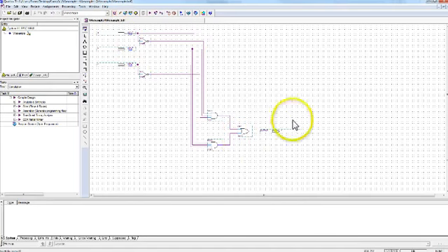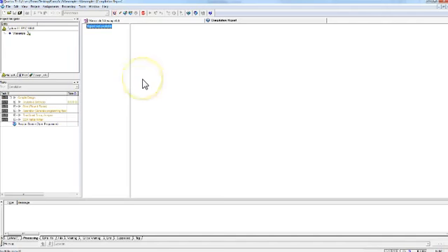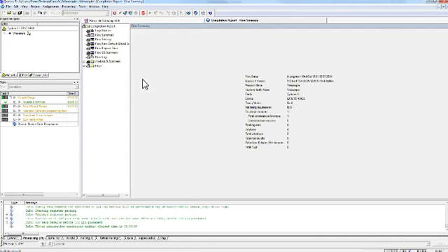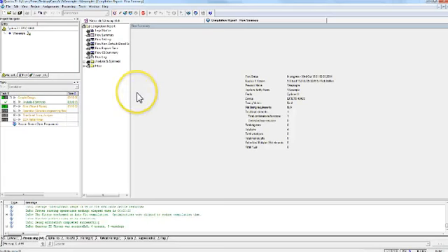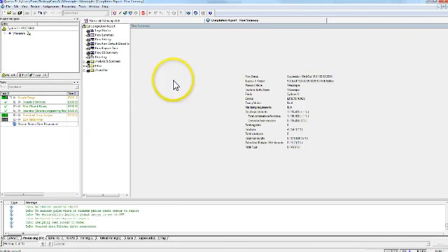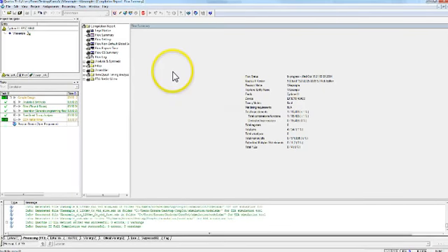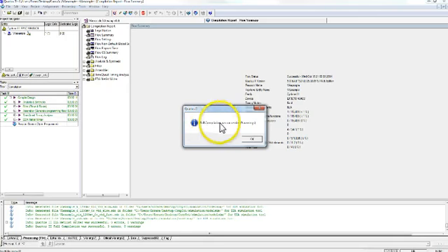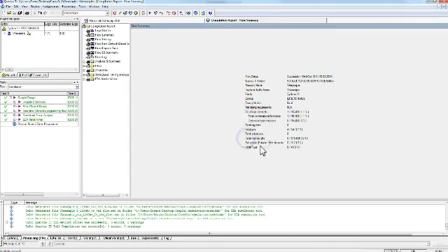And then let's see. So now we need to compile. This is the button up here to compile. This will tell us if we've made any critical errors. If it returns any warnings, you can typically ignore those. They're usually warnings about the circuit not being connected to pins yet, which is not something we're concerned about right now. All right, so we have full compilation, 9 warnings, and yeah, those warnings are about pin assignments, which we haven't done yet, and so that's not a big deal. You can sort of ignore this statistical output. It's not useful for us at the moment.